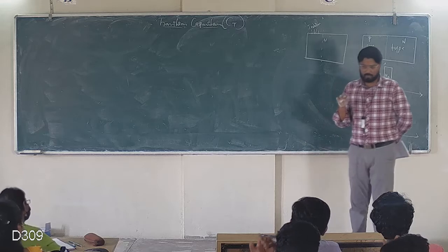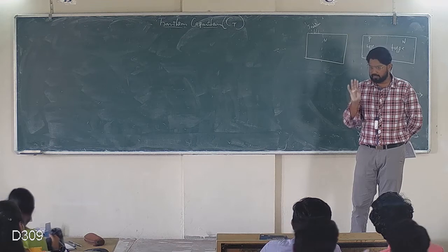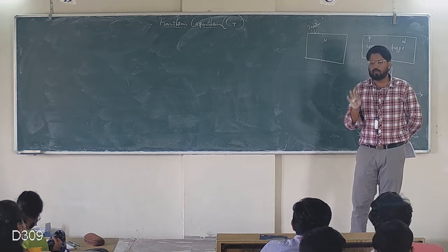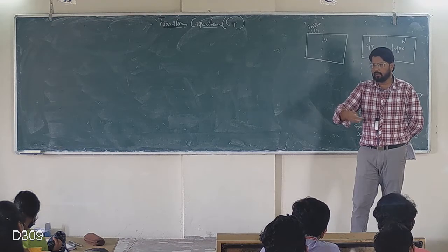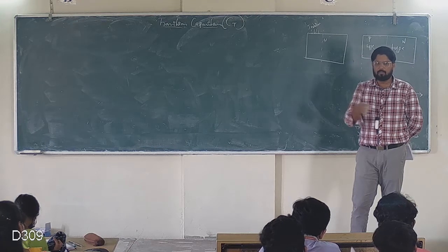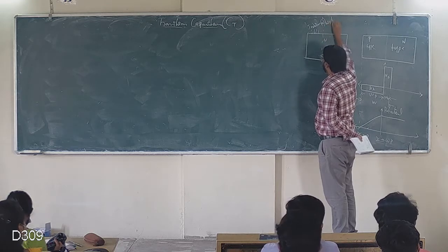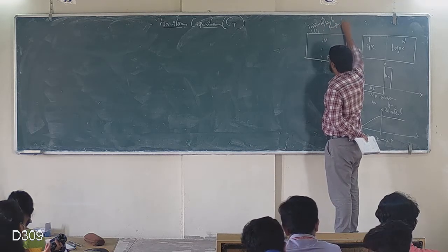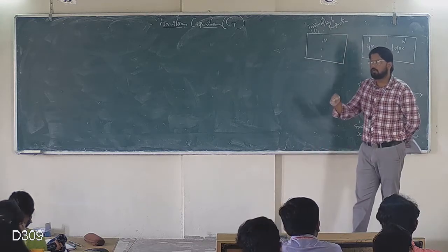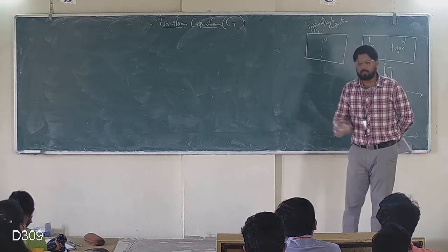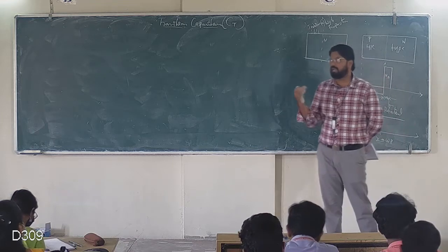Now, I spread indium. Indium is a metal. I have not taken boron, I have taken indium. It is a trivalent metal, applied or spread like a deposition over some area at high temperature. What is that high temperature? The temperature is greater than the melting point of the indium.